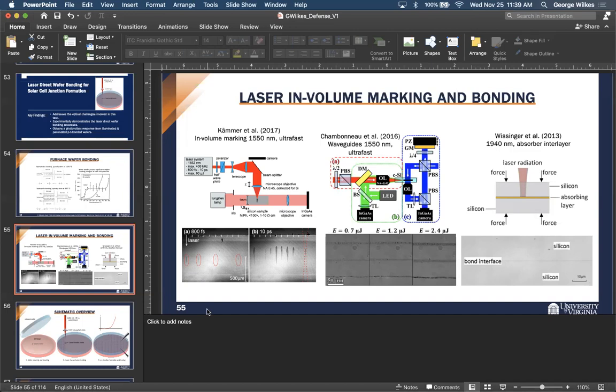Did you know why they just wanted to demonstrate the bonding, or what was the purpose of this structure? I guess it was to demonstrate laser bonding, to reduce the temperature needed to bond 2 wafers together. I don't remember what the final device was for. I think it was just for MEMS packaging or something. Okay, got it. It sounds interesting that you can actually place a different material sandwiched between silicon, for instance, right? Where you may be able to manipulate the band gap. But assuming it's not gold, but something else, a semiconductor, do you think that could work as well?